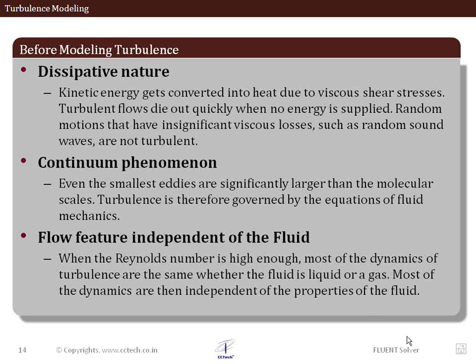So what we have to be aware of is that turbulence is also a continuum phenomenon. So continuum mechanics is still valid. We are operating at a Knudsen number much lower than 1, so we are operating in the continuum regime. The equations of fluid mechanics are still valid. The smallest eddies are still significantly larger than the molecular scale. So we are quite safe as far as capturing the physics with continuum mechanics is concerned.